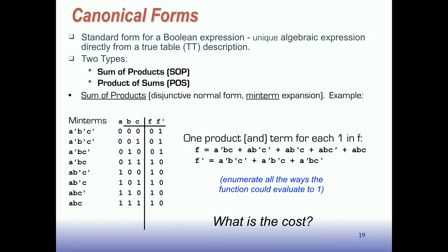So we should be able to get some estimate of the cost by counting how many gates and how big the gates are. And I'll tell you, in CMOS, it's pretty simple. Roughly speaking, each literal here, which is going into a gate, will require 2 transistors.